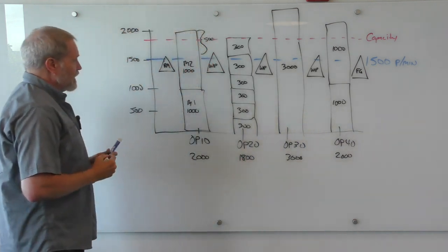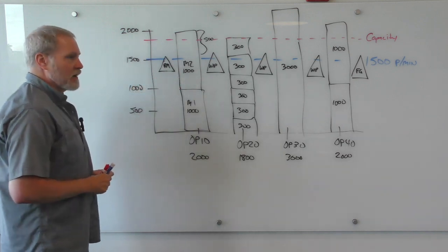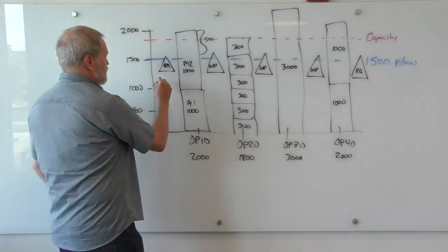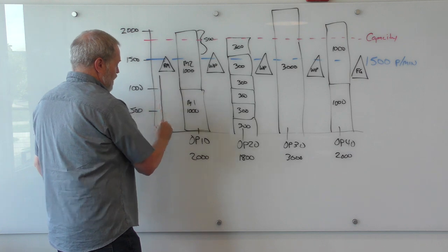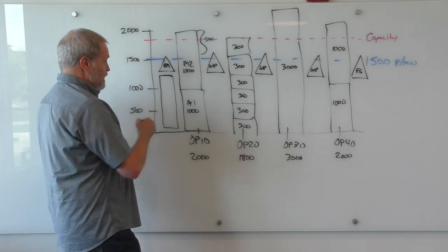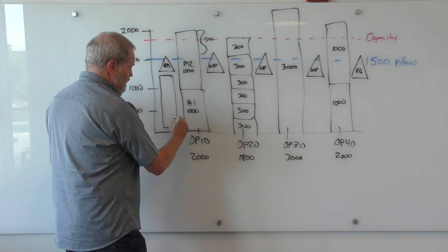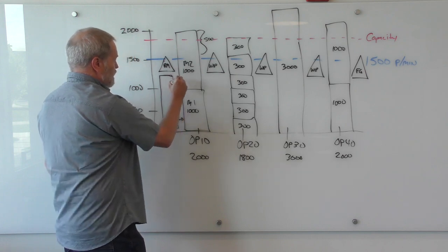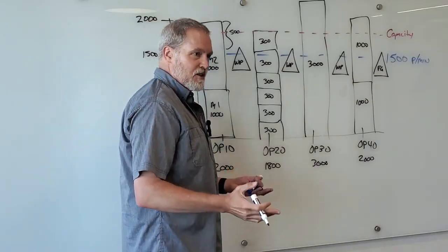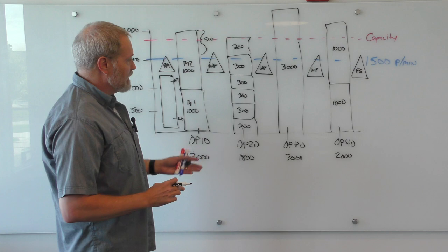Okay, so some things we need to think about here: how much inventory do we need in between there, what would be our limits, and what would we actually be aiming for? A lot of times we'll indicate this with a bar that says what is the level of inventory that I have inside of this raw material storage space on my line, and there'll be some kind of a low limit and some kind of a high limit that we're trying to monitor. Having this queue completely full is not necessarily good. Having it completely empty is not good, but it is different at different stages.